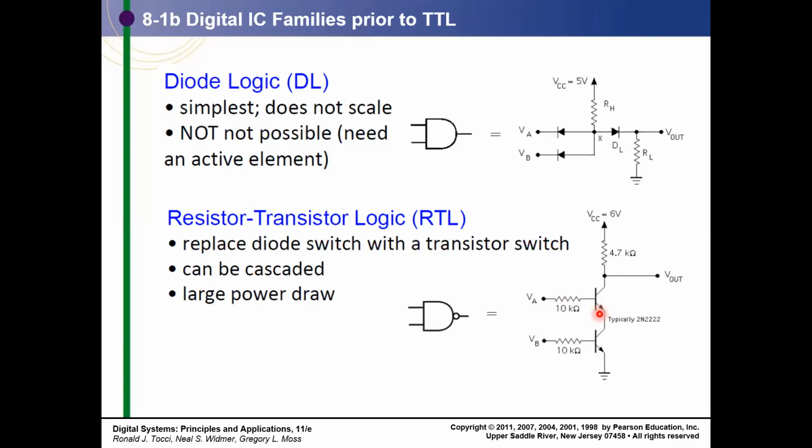So it cannot turn on. The transistor will switch off, and if the transistor switches off, it is like an open switch, and therefore this node cannot sink. So this node will reach a high voltage. Whatever is here, the same voltage should reach over here, because there will not be any potential drop in that condition.